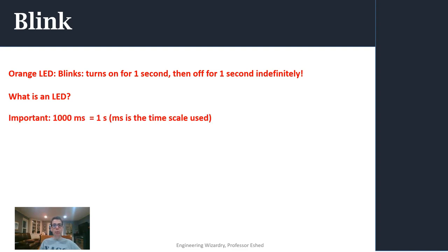All right, so remember the time units in our commands are milliseconds, and 1000 milliseconds is 1 second. That's important. Now here's an interesting question: how does the board know to do that? We didn't upload that Blink software onto the board, so how does it know? Just connecting the board with the USB cable to your computer doesn't upload the code you have on your screen. You really have to hit that right-facing arrow to do that.